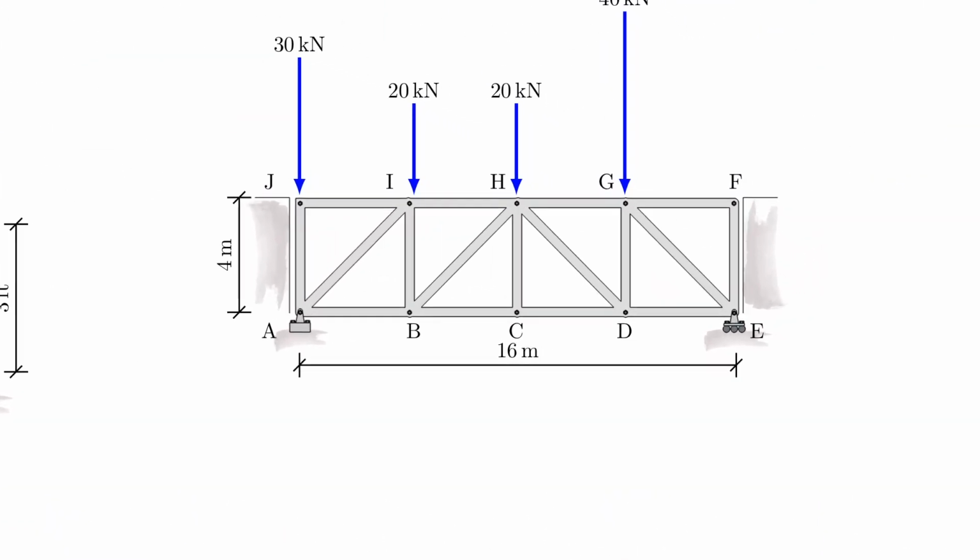So this one here on the top, what do we have going on here? I would say we definitely have a zero force member here because parallel and an unloaded third one. So let me make that disappear. So that's gone now. Do I have another one? Yes, I do. And that's a little bit deceiving again. I actually have two more ones because here I have actually the second case that we discussed, and that is the external unloaded node here. So there's an external node unloaded, therefore this has to disappear as well.